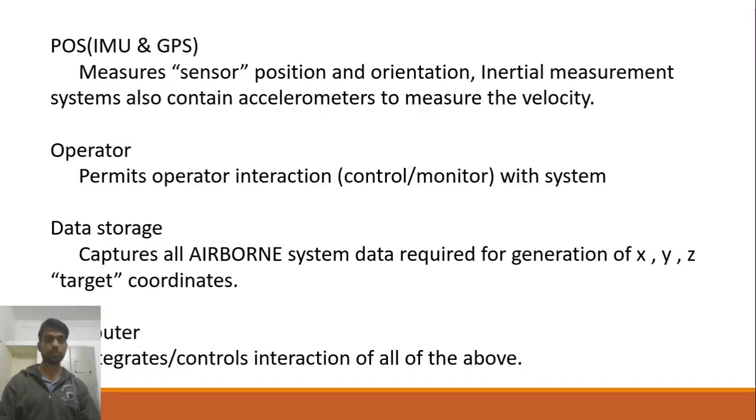Moving on, positioning systems are a very important component. When a light detection and ranging sensor is mounted on an aeroplane, satellite, or automobile, it is necessary to determine the absolute position and the orientation of the sensor to maintain usable data. Global Positioning System provides accurate geographical information regarding the position of the sensor and inertial location. These devices provide the method for translating sensor data into static points for use in a variety of systems. There is operator interaction which controls interaction with the flight controllers in the case of UAVs.